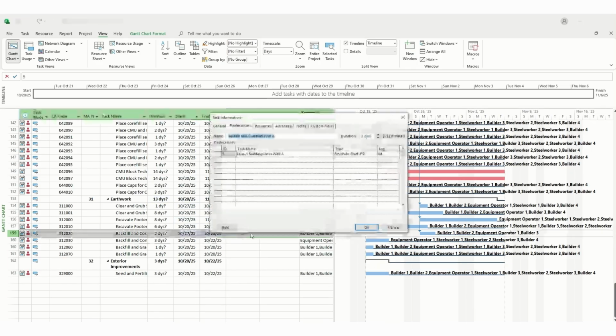Okay, click on it. You can either do a lag. The lag is for working days only. So let's say you want a 7-day break, so you want it to lag 7 days so you can have that break test done before you remove forms.